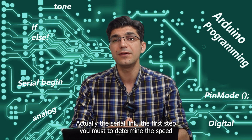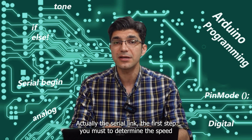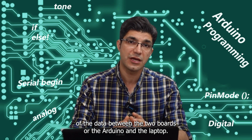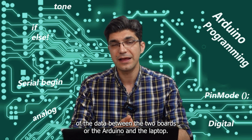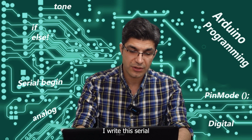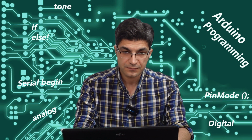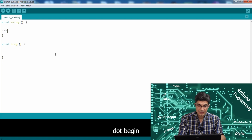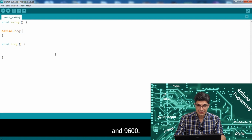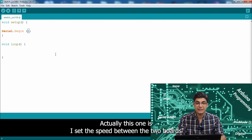For the serial link, the first step you must determine the speed of the data between the two boards, or the Arduino and the laptop. This is possible in the void setup. I write Serial.begin 9600. This sets the speed between the two boards.